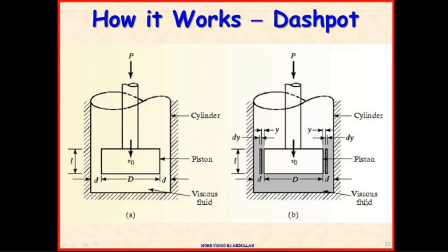If you observe buses, for example, the public transport, they have air suspension, isn't it? And the other one is fluid suspension, isn't it? You find that the air suspension is easier to control than fluids. With air suspension you just control the valve to decide how much air goes into the volume. So if you are an engineer, you know that the bus can carry 40 passengers, for example, or 30 passengers, but sometimes there are only 1 or 2 passengers in the bus.